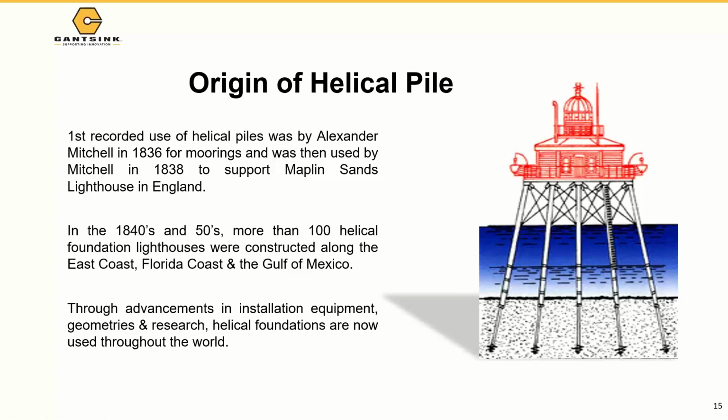And the reason why I said they became so popular in the last 30 years or so is because of the advancement in installation equipment. Nowadays, we have these hydraulic machines. We can install almost any type, any shaft size. As a matter of fact, about 10 years ago, ExxonMobil from Canada sent me a 1-foot diameter shaft with a 48-inch helix diameter, and they wanted to test it to see the helix capacity.